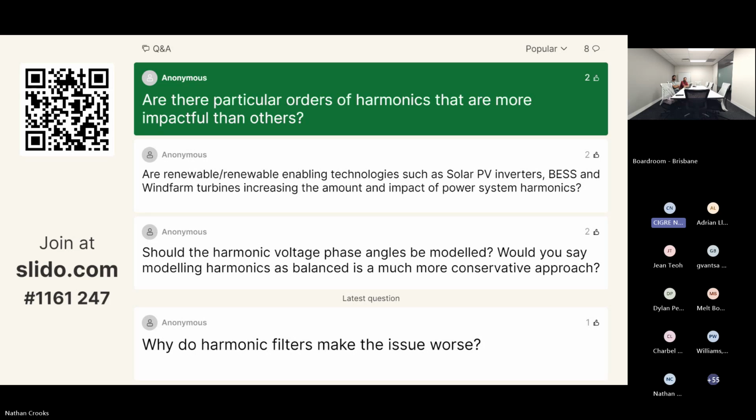So what I'm saying is that 0.1% is not going to destroy things before your eyes. They need to be there in quite a substantial amount, depending again on the size. For some big piece of equipment, at 2-3% you start seeing bad effects. For something smaller, like in your house, 10%. Have you seen the waveform in my house? I don't have fire coming out of my appliances. If you apply that voltage, everything keeps functioning more or less happily. It is built also to put up with that amount of distortion. So that's it.